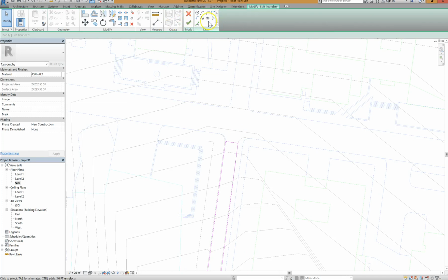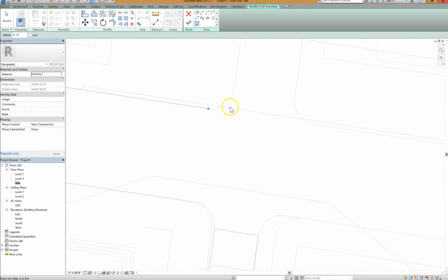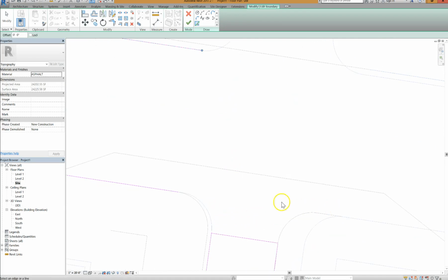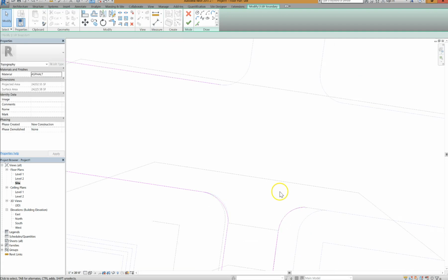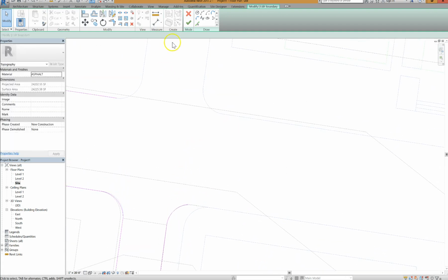And then I can just trace out the roads basically. Do that. It doesn't want to do the corners. Since it doesn't want to do the corners, what I could just do is use this arc command here. Make that. Escape, break that. Come over here. That arc. I'll remove this piece since we're now adding on to this. And then I'll go back to my pick lines command. Pick that line. Pick that line.